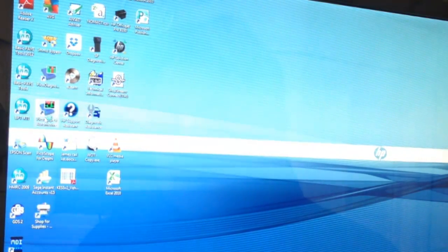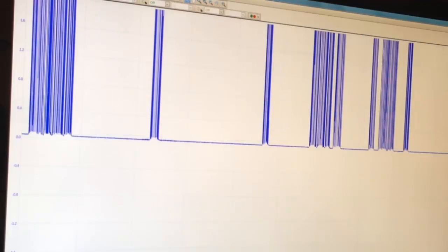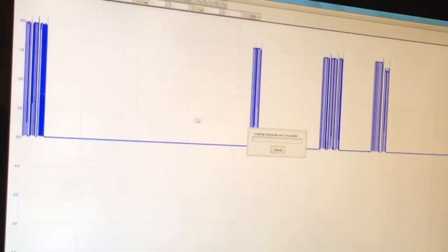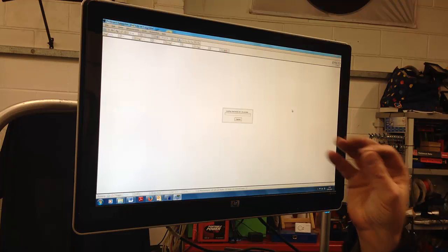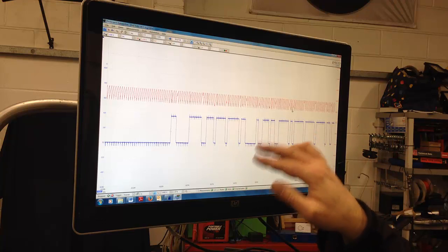What I wanted to do now is just to hook up to Pico, so I'm going to fire the PicoScope software back up. We saved the capture yesterday of the vehicle that we had with the faulty waveform. So if I select File, Open, Bad Body CAN, 1 millisecond time base. Just to give ourselves a quick refresher, this is what we had in terms of the waveform with the old module plugged in. We've just plugged the new module in.